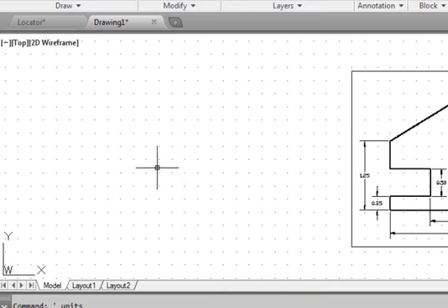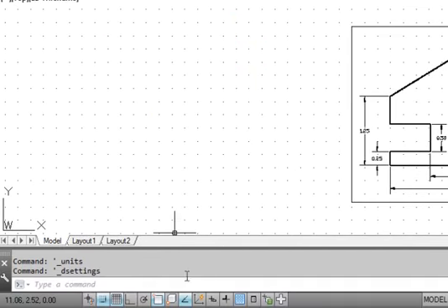Now in the status toolbar, turn off all the different options, but just have the snap option and the grid display option turned on. So looking at the screen, we will know that the distance between 2 grid points is exactly 0.25 inches. So let's begin to create our design.